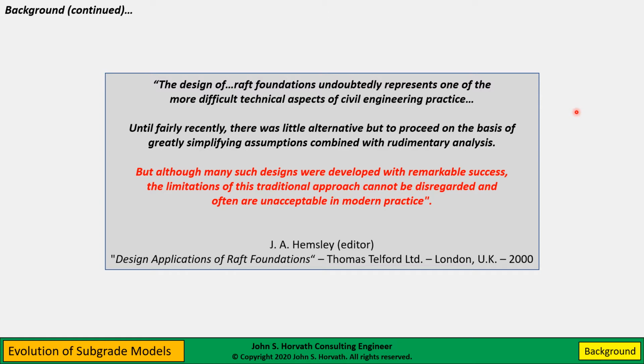We used beam on elastic foundation and Terzaghi's coefficient of subgrade reaction values because we didn't have any alternatives. And yes, certainly if we look at some of the case histories I'll show you later that were designed on this basis, they have performed satisfactorily for the last almost 60 years. But that doesn't mean we need to do that today.